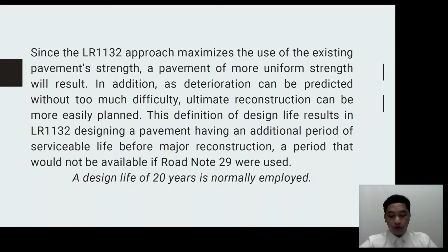The definition of design life results in LR1132 designing a pavement having an additional period of serviceable life before major reconstruction, a period that will not be available if Road Note 29 were used.